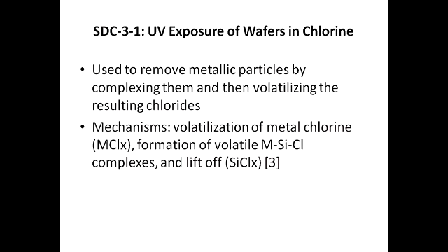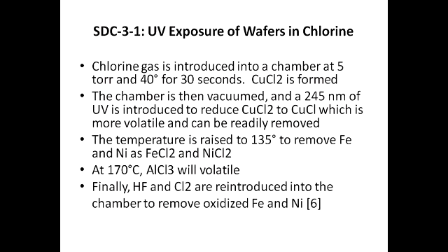There are 3 mechanisms: volatilization of metal chlorides, formation of volatile complexes, and lift-off. It's the first part of the third step. First, chlorine gas is introduced into a vacuum chamber at 5 torr, 40 degrees for 30 seconds.